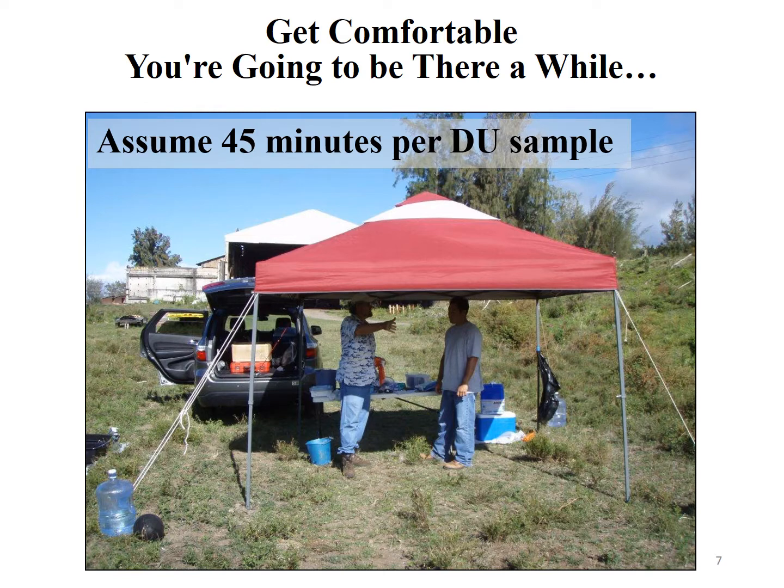With some experience and the right tools, DU-MIS samples can be collected in a reasonable time frame, approximately 30 to 60 minutes per DU, though this assumes the site is clear enough to navigate, soil is accessible, and you have pre-planned and located the DUs in the field. Typically, the biggest factor affecting sampling efficiency is the tool selected or available for sampling and how fast each increment can be correctly and consistently collected with that tool.